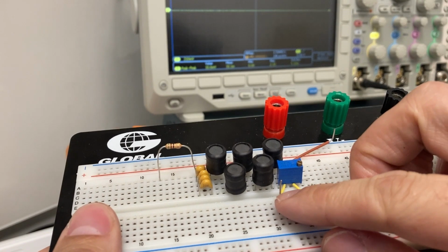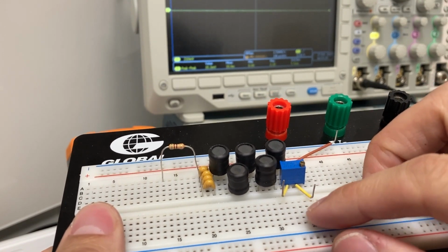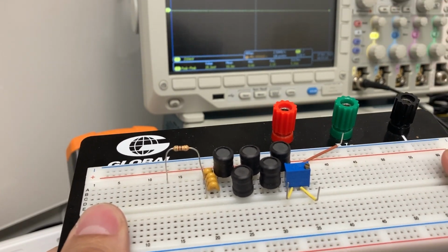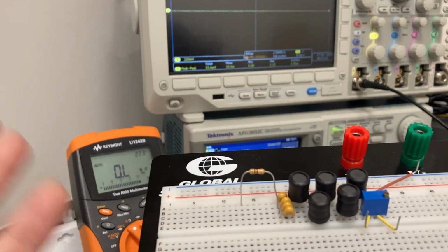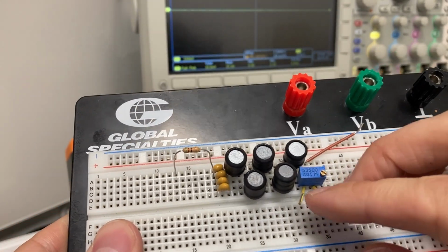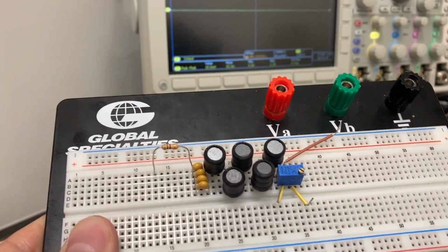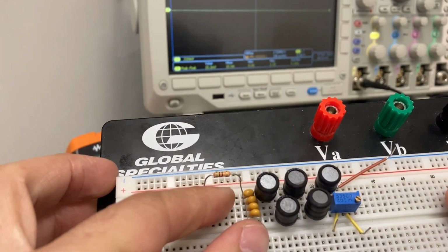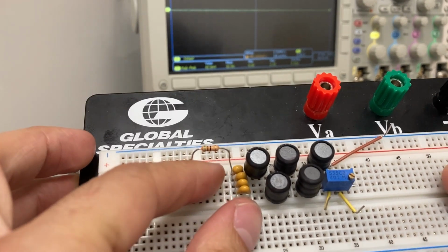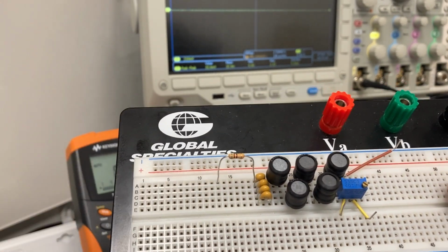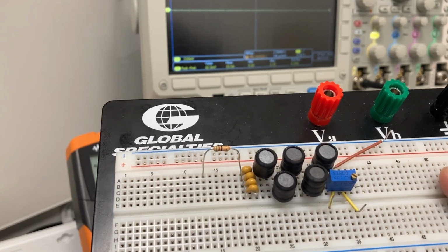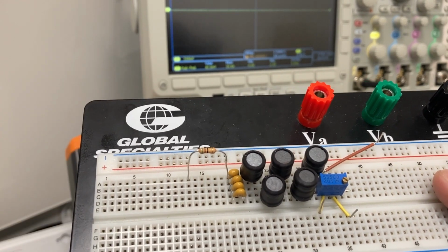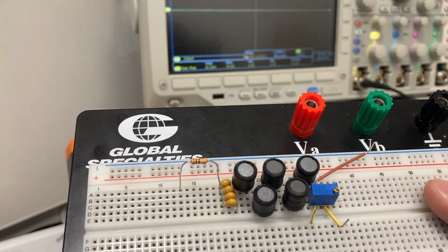I did add these 2 little leads here to the legs 1 and 2 on the potentiometer, so I can just get a resistance measurement very quickly and then go back to my circuit. And I'm working with just 1 multimeter, but in the lab you could use a couple so that you have 1 dedicated for resistance and 1 you can use for the current measurement. In any case, I had to put all of these capacitors in parallel because I'm trying to add them up to the value of 2.364 microfarad. What I actually ended up with when I measure it on the LCR meter is 2.27 microfarad.